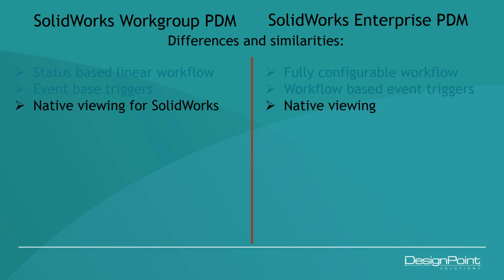If you want to preview files with Workgroup, you can basically preview SolidWorks files. If you want to preview PDFs, you have to have Adobe Reader or Foxit Reader installed. Other types of documents have only thumbnail bitmaps. With EPDM, you have over 400 file formats that you can view. There are ActiveX compliant viewers that can be installed to support other formats. You can also preview PDFs and Office documents without even having the application installed on that machine.